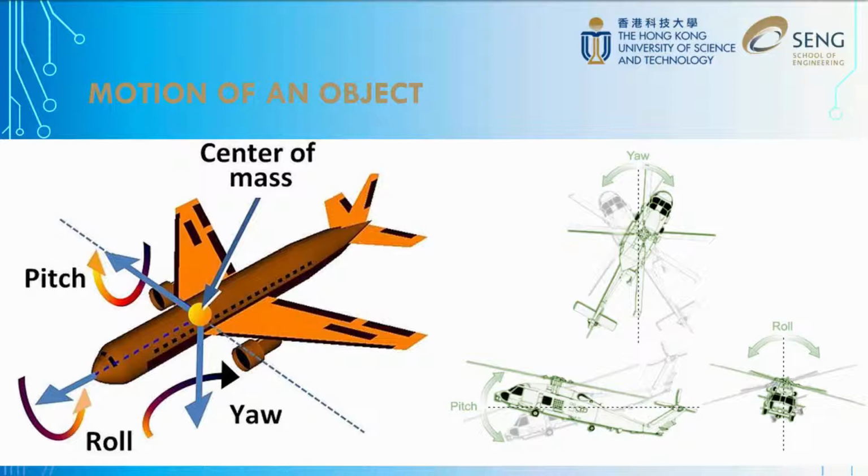That said, identifying the location of the mass center is always the first step in mechanical engineering design. In practice, you can always use a finger or a string to test out the balance points, and thus the center of mass, of your prototype quickly. And this is very important in the exercise. Try to do it as frequently as possible to give you a better understanding about where the center of mass is, and then use it to predict the motion of your prototype.